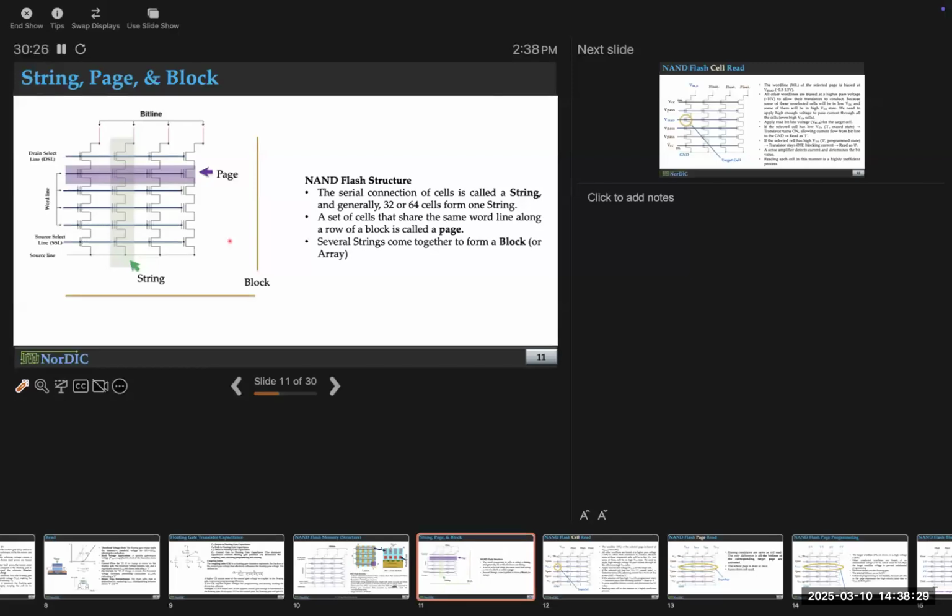So in NAND flash, we typically read out every page. So basically, when you read, we read the entire row at a time. And there are reasons. You can, with great difficulty, read individual cells, but it's not useful, so we don't typically do it. But if you need individual control, then NOR memory is your option. NOR memory is faster, random access. NOR is faster. NAND is slower.